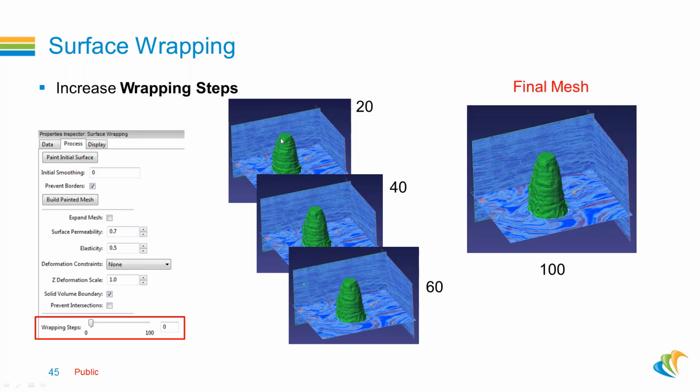So this wrapping step is helping us go from a very rough connection between different depths of our interpretation to smoothing the geobody and finally getting the image all connected and all smooth. So this is the second way to interpret the salt body. One is only a few clicks, and with the second one you can get a little bit more control, of course doing it step by step.